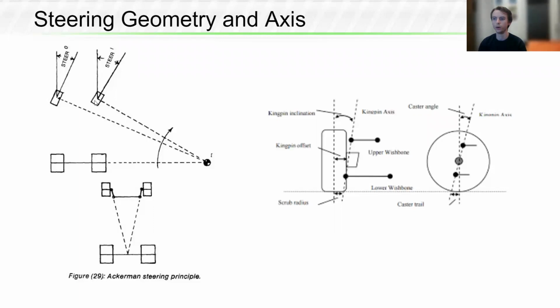And so the angle at which the tires are pointing is different, which changes where the slip angle is of your tires. So you're not traveling in a perfectly uniform arc. And that influences where we place the steering points on the outboard suspension.